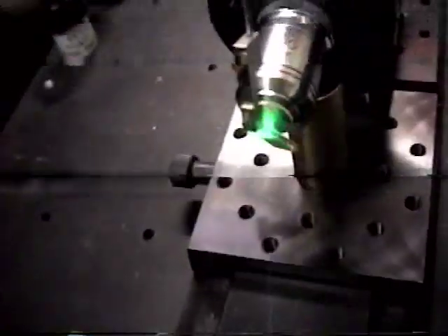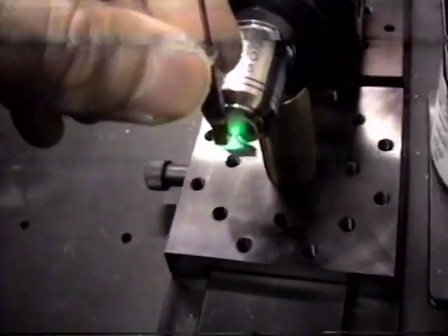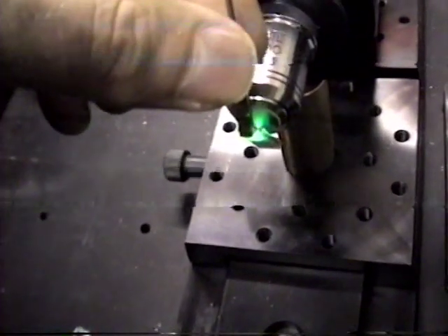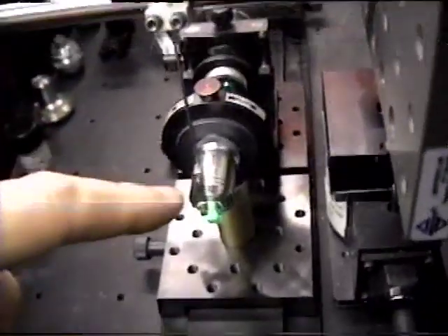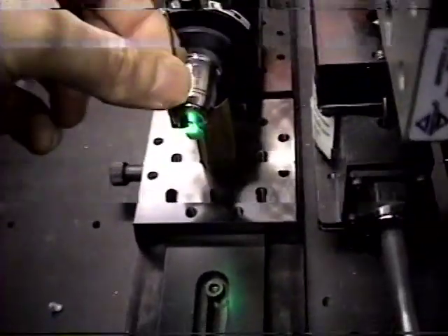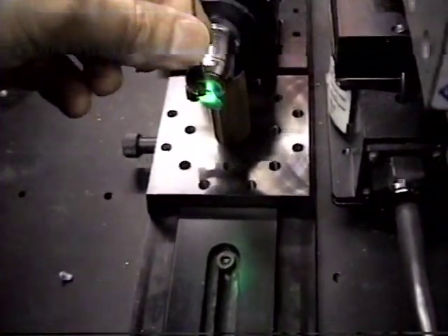One other thing to note is that you have to take off the jacket sometimes in order to expose the fiber, and the real easy way to do that is just to take a razor blade and gently score the circumference of the jacket, and then just pull. It breaks very easily after being scored, exposing the cladded fiber. It took me a while to figure that one out, but it's very easy to do now that I know how to do it.